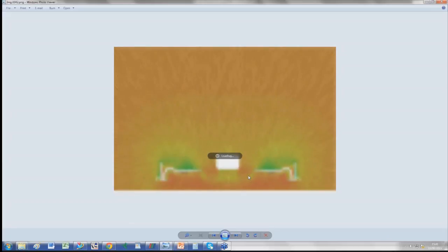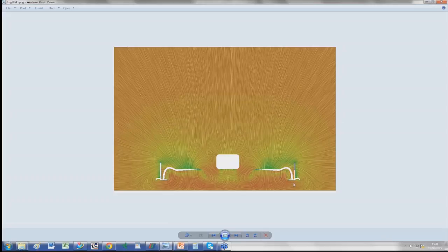On the other side of the front wing, the same is happening. Obviously, this is the end of the front wing. The air wants to rotate around and go under, just due to suction effect. So you can see that you've got a big vortex in one direction here, going this way, and outboard you've got another one going the other way. Actually, you can even see that this one is split in two vortices. You've got a small one in this sort of tunnel, and a second one created in this sort of pocket.